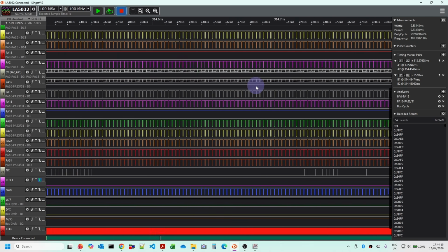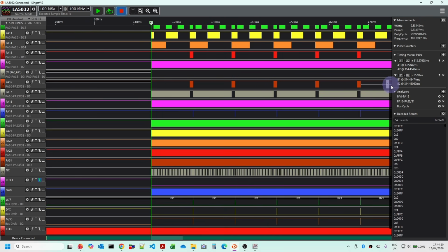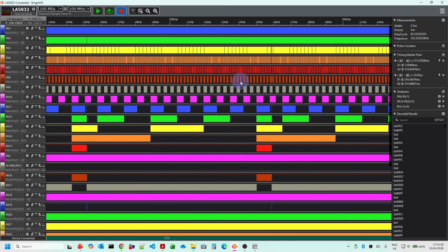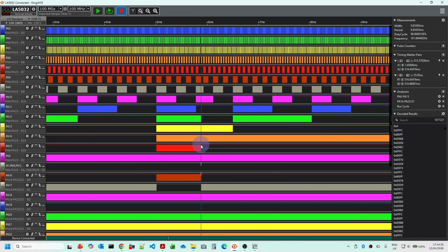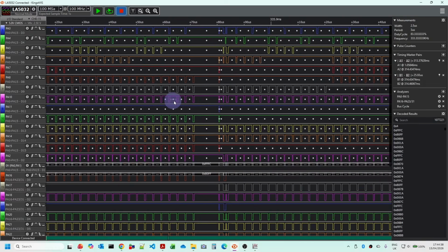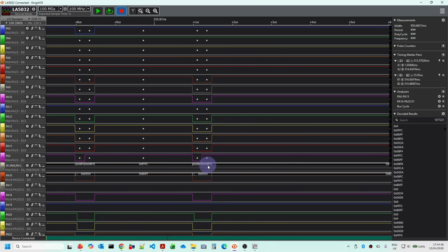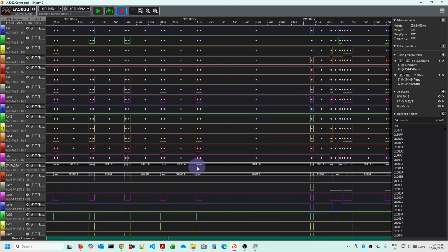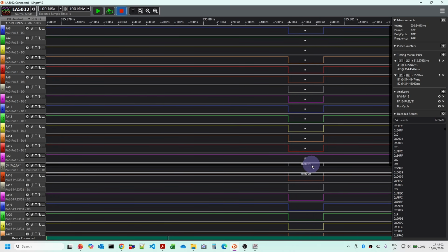It's not particularly easy to see, but if we have a look at the high level, we can see that our address lines are going in this sort of pattern. This is what we'd expect when we've got binary data going up in sequence, as it were. Every now and then we'll find that there'll be another gap here. And so I think what we'll find, if we drill in here and look at the last bit, we can see that we've got 08FB, I think, there.